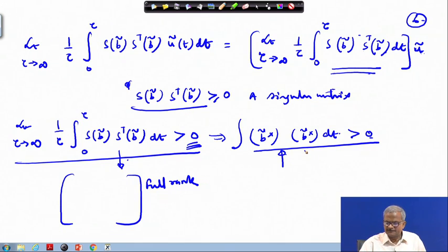So, using this magnetic attitude control, because it is quite simple, I am trying to show you how to design a control, and obviously for this we need the Lyapunov stability analysis. I will briefly introduce you. I presume that you know, because those things are taught in your basic control course. So, here this is 1 by tau, limit tau tends to infinity.